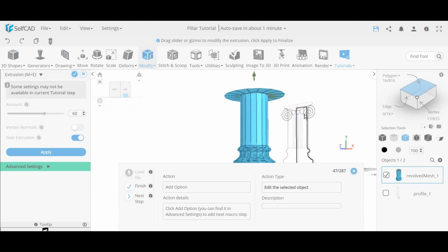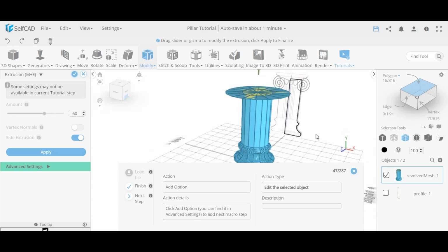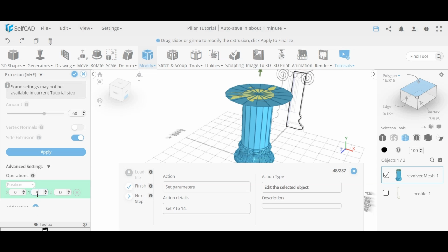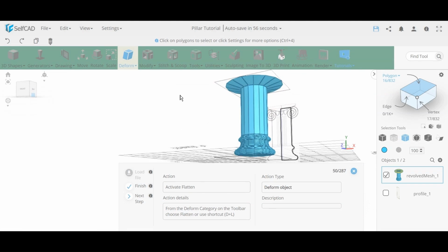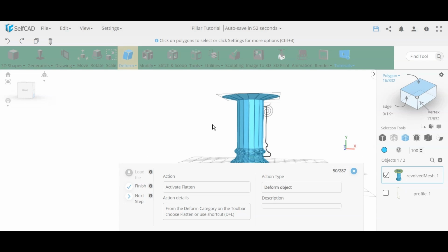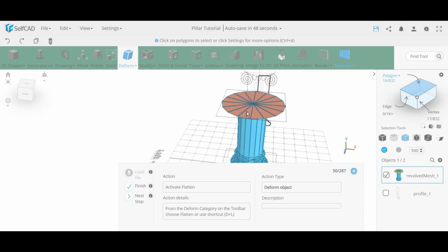So this is not really manifold yet. There are 2 ways to do something like this when you want to extend and make it manifold. One way is to simply move it up, which this is going to do over here. It moves up the Y to 14, and then it's finalized. So this by itself is already manifold. I can finalize this. We still have not solved the problem of making this, it's still rounded. We have not solved this by making them flat, rectangular. So we're going to solve this in a moment.